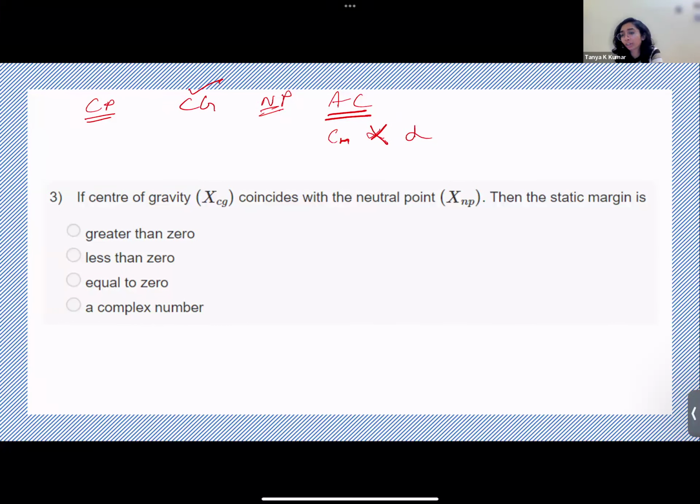How is it different from aerodynamic center then? Both are the same, right? I think this would move a lot faster if you just unmuted yourself and answered, because typing might take time. You were told that aerodynamic center is the point about which moment is independent of angle of attack. Now when I asked for neutral point, you said Cm alpha is 0. Isn't that the same thing?